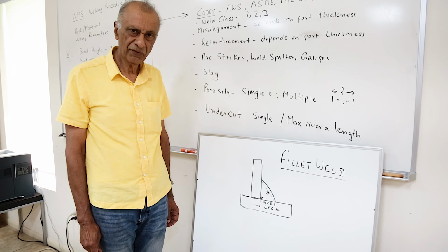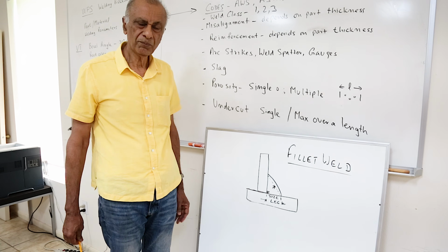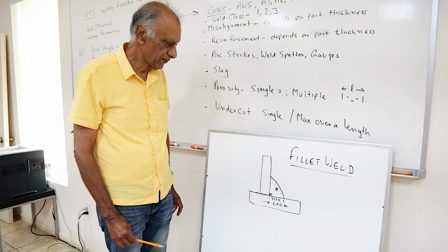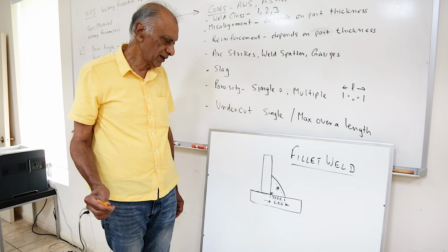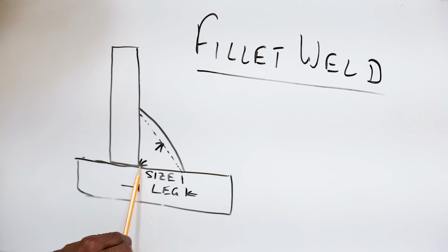This additional item is the fillet weld. The ones we just did were all butt welds. Fillet welds are very common in structural weld inspection. So in structure, they're very common. Really, all you're looking for in the fillet weld is the size, which is from here to there.